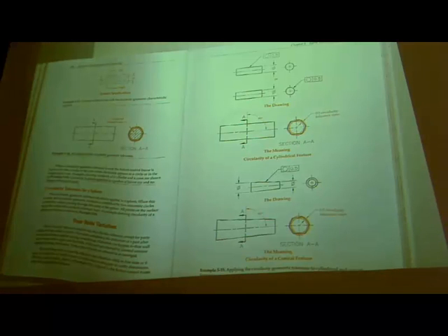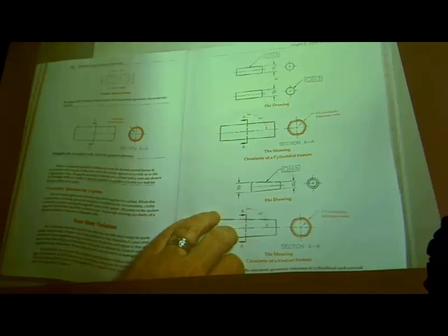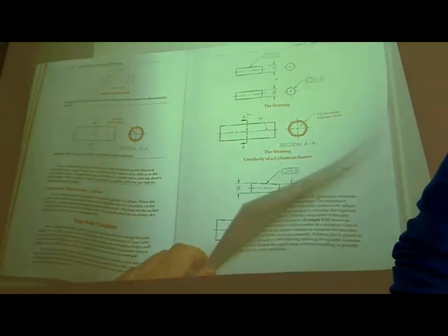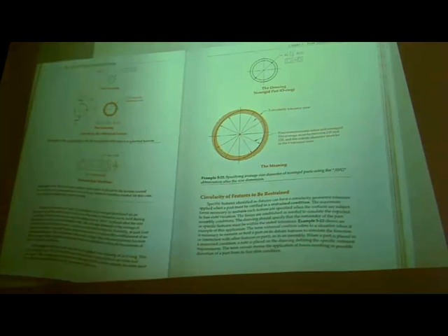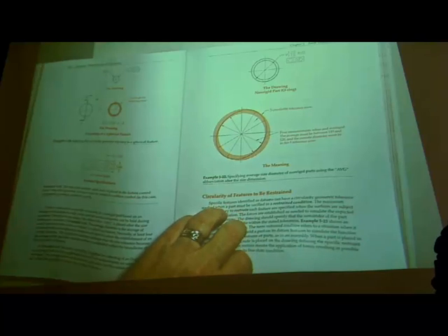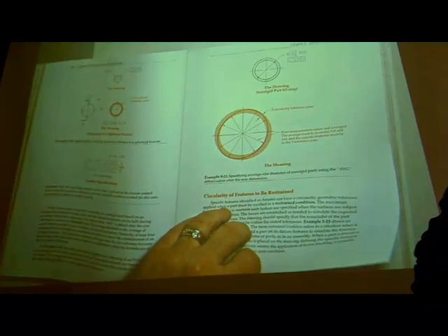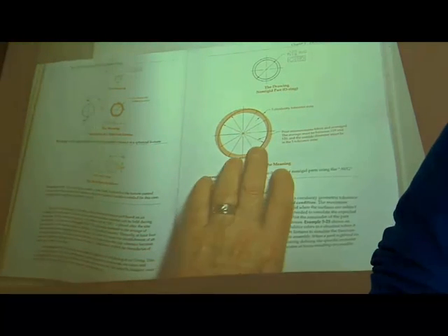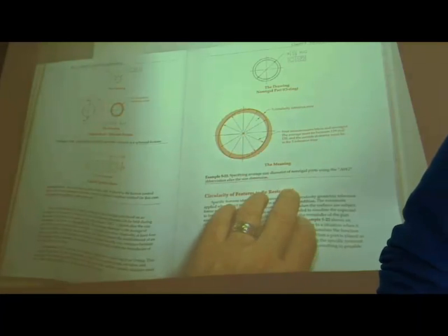Then circularity, 2 concentric circles, regardless of feature size. No datum reference required. Then cylindricity. Then we also use circularity for non-rigid parts, thin non-rigid parts.